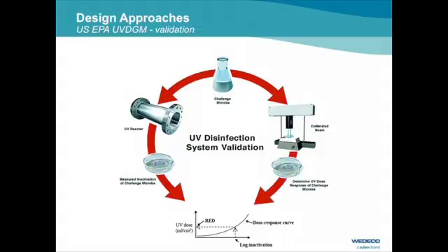And in this way, it's not a uniform dose anymore, but it's called a reduction equivalent dose. That means it's always related to a certain reduction achieved with this specific organism. So this is also a change in understanding. There is not only a dose of 20 or 30 or 40 or whatever, but in order to understand what that means in terms of log reduction, you always need to tie it to a certain organism and its dose response behavior, because that's the way it was established.